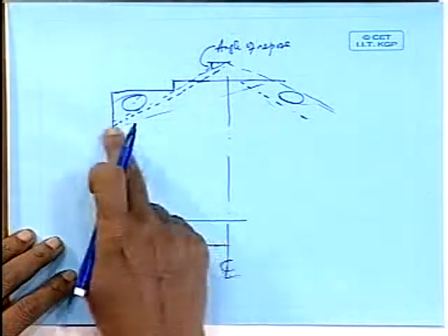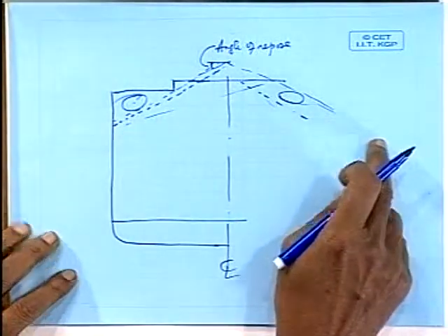You have got that small i divided by V, that was derived. So you know that because of the triangle moving from one side to the other, the loss of GM is there because of that. Same thing happens here. Now this is very large because it happens across the entire width of the ship. So what can we do?